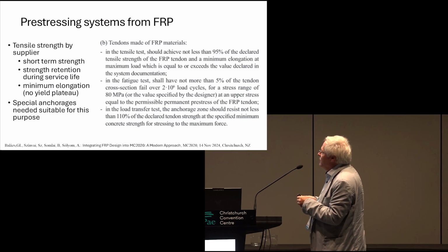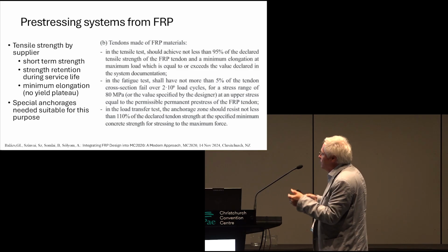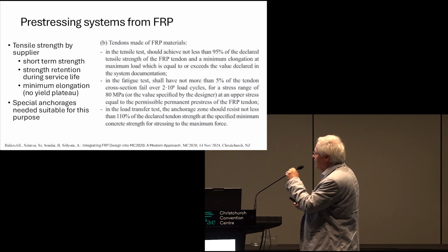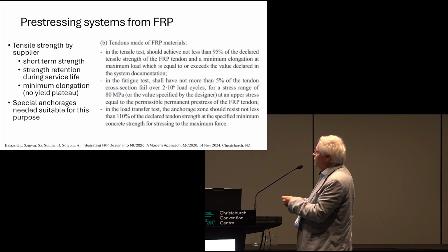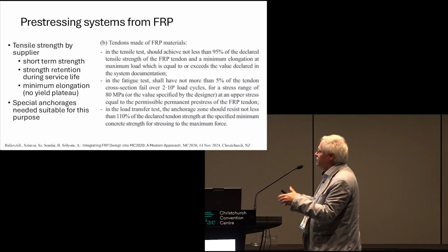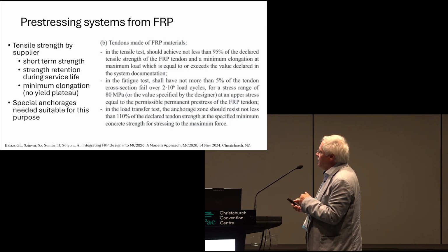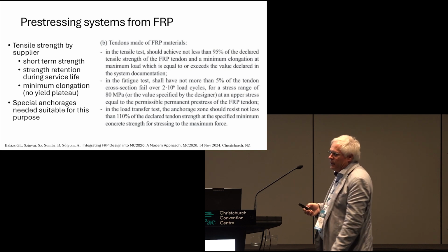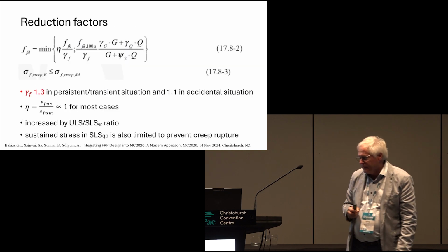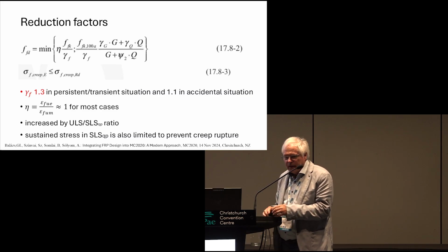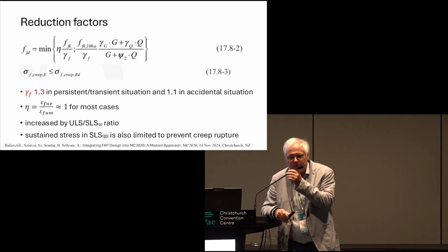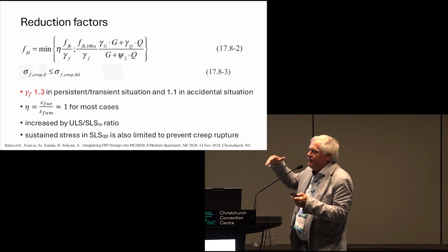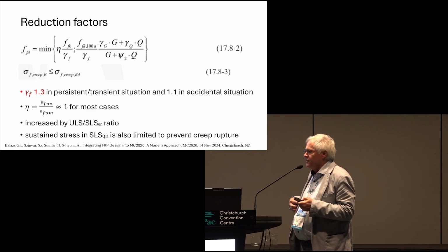Relaxation is not so problematic. As I mentioned, this is a kind of summary. We should not go again into details. The anchorage problems have to be solved before the application, and the long-term strength is important. The safety factor was already a very long discussion, and you were able to find different safety factors from that value which is given in Model Code 2020 for every case, which is a good approach and easy to apply.